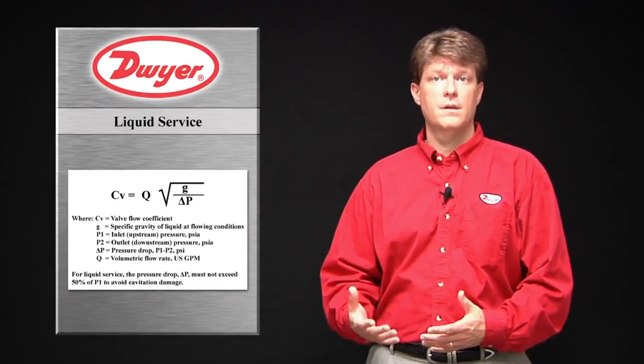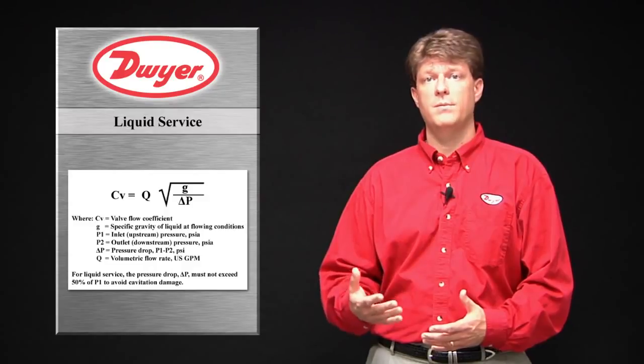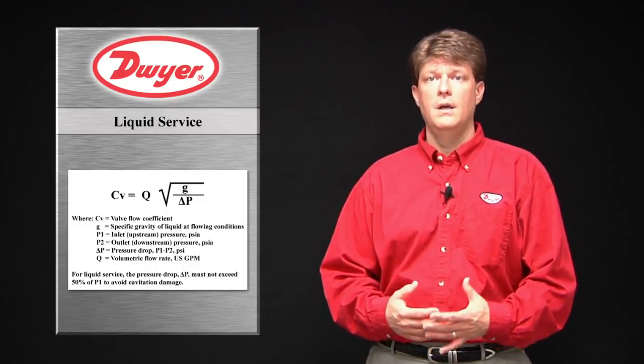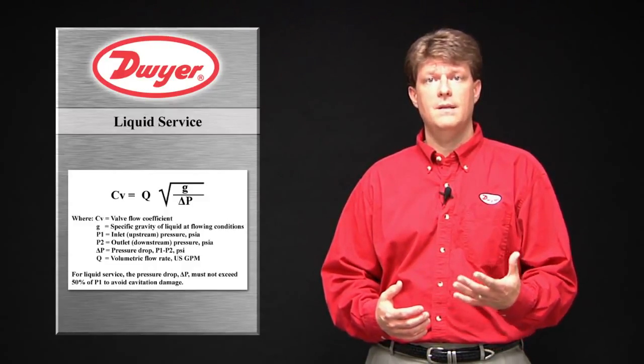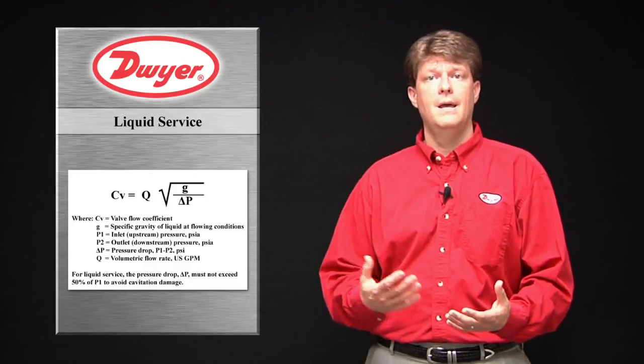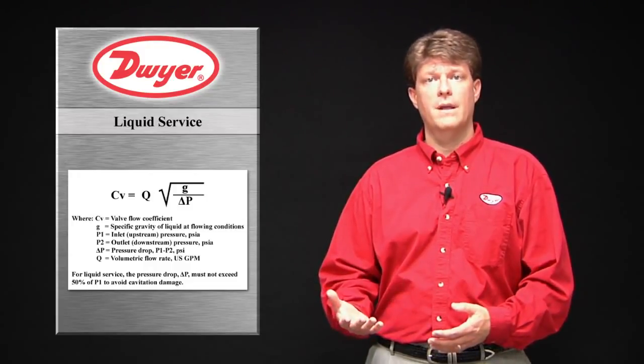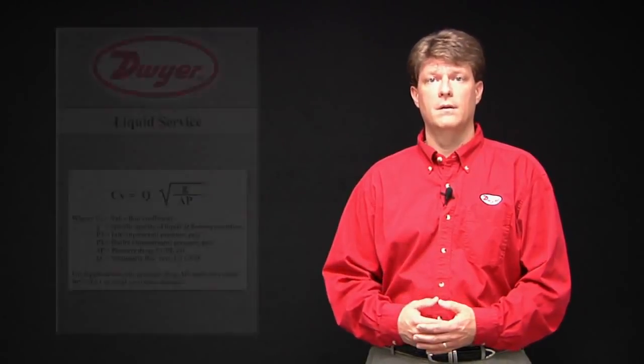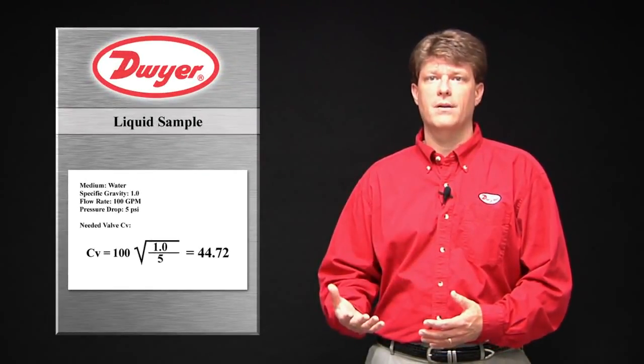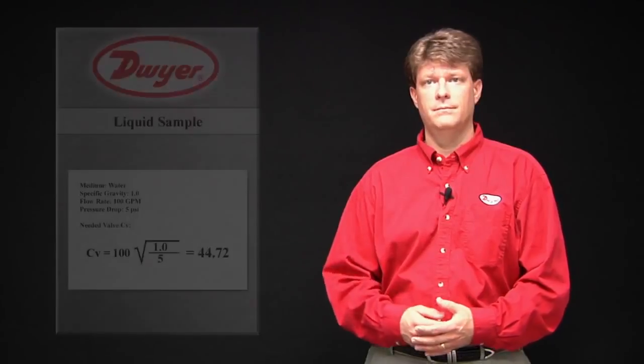For liquid service, the pressure drop must not exceed 50% of the upstream pressure. Use the equation shown with CV dependent upon upstream pressure, downstream pressure, pressure drop taken, volumetric flow rate needed, and specific gravity. Here's an example calculation for a liquid application.